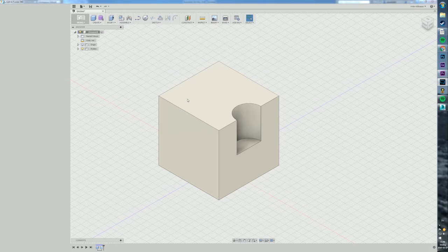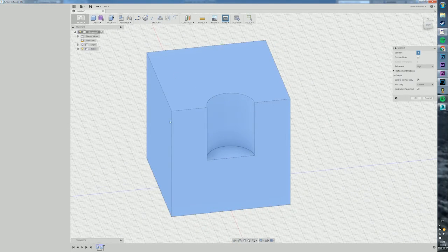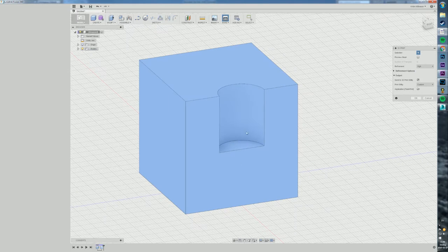Anyways, polygon models are based off a lot of triangles and multi-polygon surfaces, so they only have flat triangles. There's no bending involved, there's no smooth surfaces. So every radius, for example, needs to be defined by a lot of small triangles. So let's start off here by showing you how it converts or looks within Fusion 360. So I have these flat surfaces and I have this radius in here.